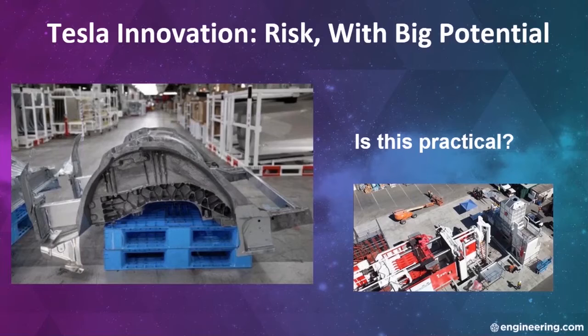Now, obviously, replacing an entire front or rear clip after a minor bump impact is going to be a non-starter with the insurance industry. And as a result, Musk has announced service kits are going to involve cutting away damaged extensions and bolting on service kits. On top of all this, there will still be a fairly conventional unit construction body shell, but it's unknown if that body in white is going to take some of these structural loads. Now, I expect it's going to contribute significantly to resisting torsional moments at least.